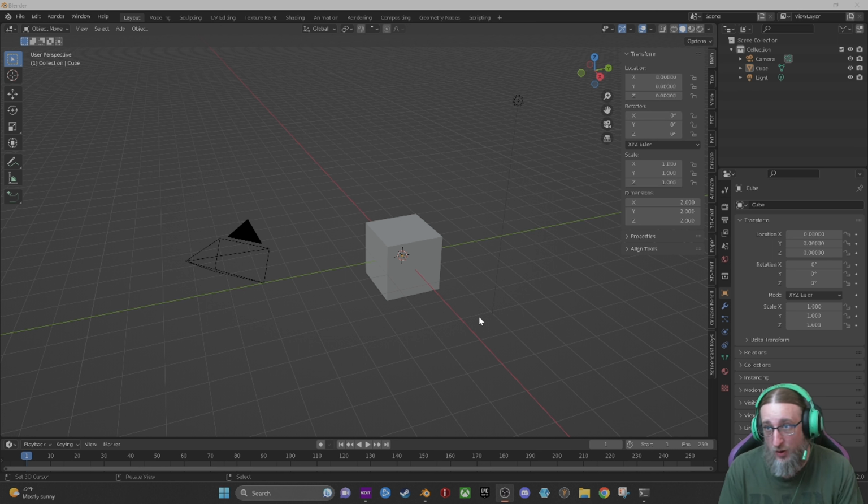And then I'm also going to turn the strength down to 0.02, just because when I bring it in, I don't want it to be super lumpy and not be able to tell what stuff is. So I'll turn my strength down to 0.02 and I'll change my coordinates to UV. Now, once you click on UV, you also want to click on the UV map and then just select the UV map.